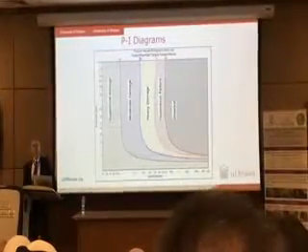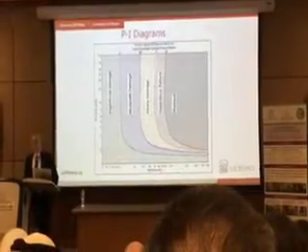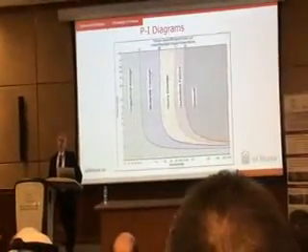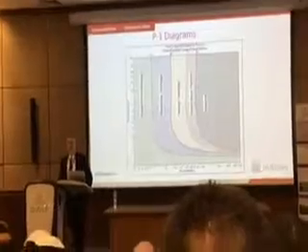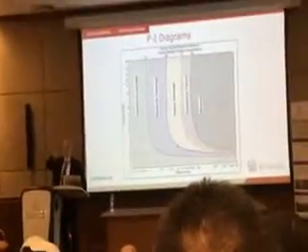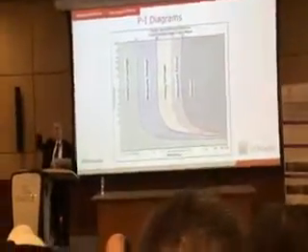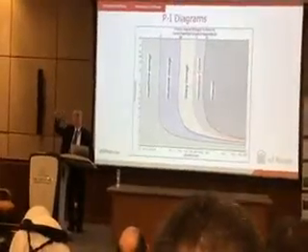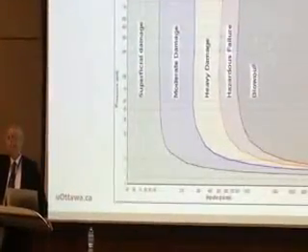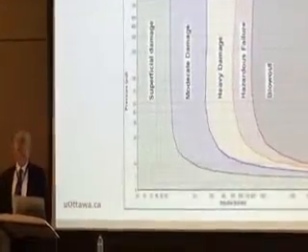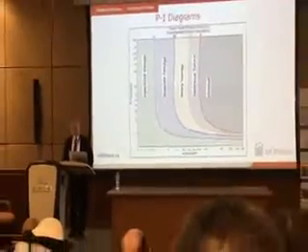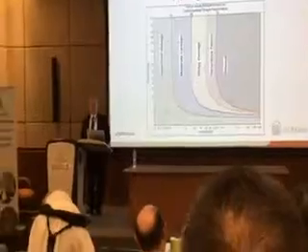Now, one other very, very important design concept and design tool is PI diagrams. When we design reinforced concrete columns, we have column interaction charts, right? PM, so with design moment and design axial load, we make sure that it's inside the curve that indicates it's safe. Similarly, there are PI diagrams generated for different members.